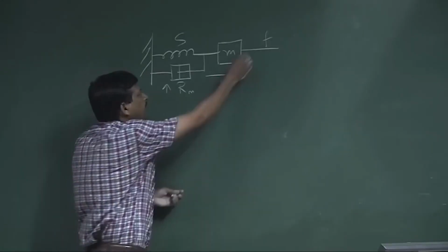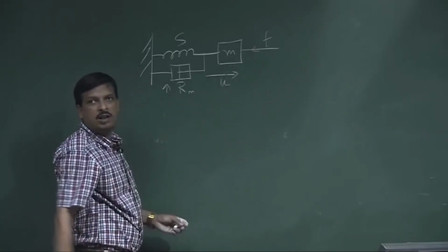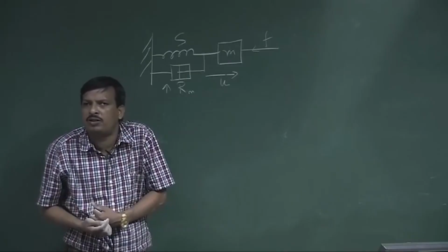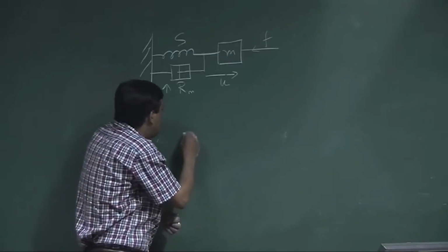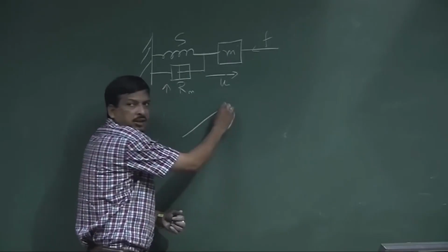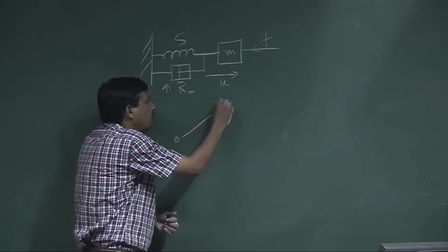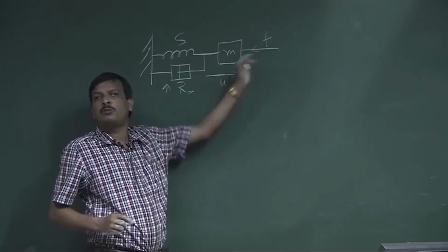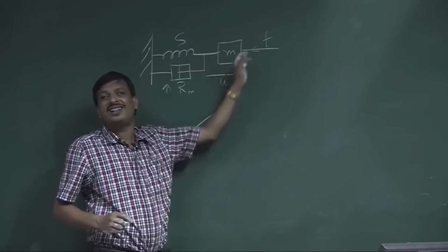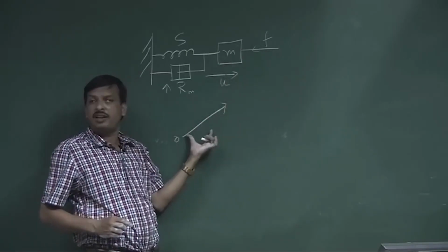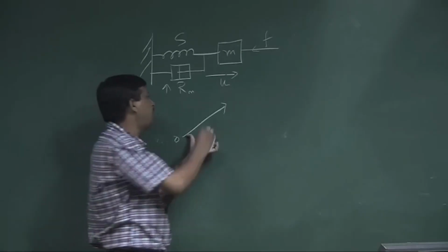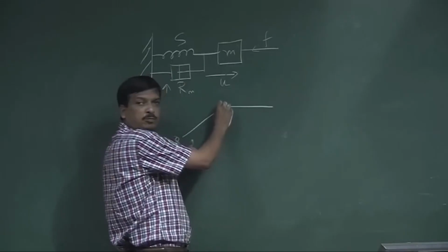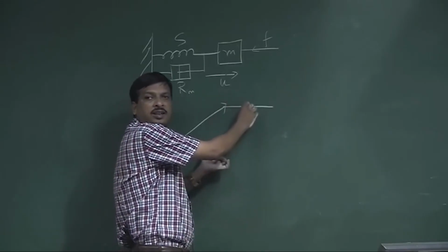When I apply a force, then and there it cannot oscillate as per the force frequency. So, there should be a transitory portion from the rest position until it reaches steady state, when it will oscillate as per the force frequency. So, to reach that steady state, I require a transitory portion. Forced oscillation has two parts, the transitory portion and the steady state portion.